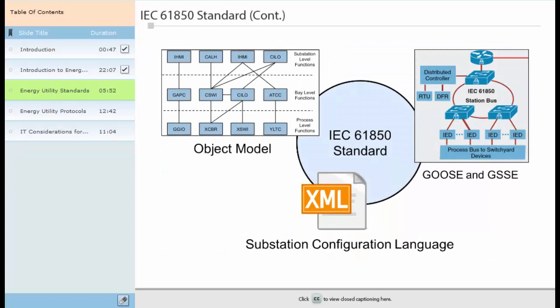The core components of the IEC 61850 standard are as follows. An object model describing available data from various primary equipment and from the automated substation functions. To accomplish this goal, the functions of a substation are divided into subfunctions called logical nodes. LNs are the core element of this data model.